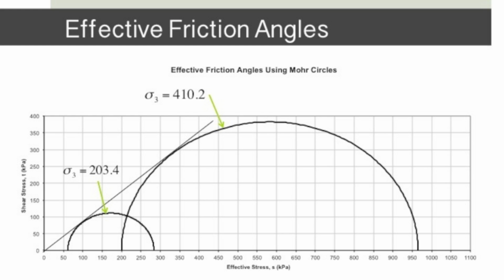Notice how the far right-hand side of the circle intersects the x-axis at this point. The next selected point is the minimum principal stress, which is 200 kPa. If we connect these 3 points, a circle should form with the center being about the average of the minimum and maximum principal stresses. Next, the line tangent to both circles is drawn.